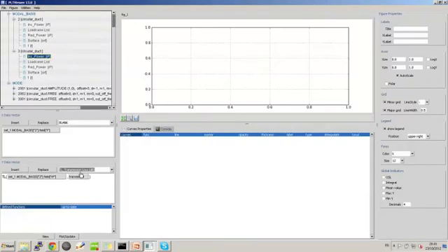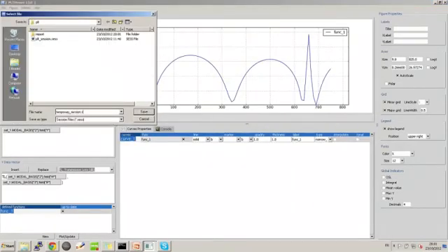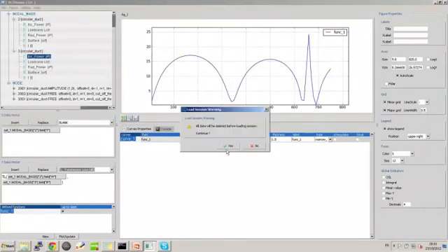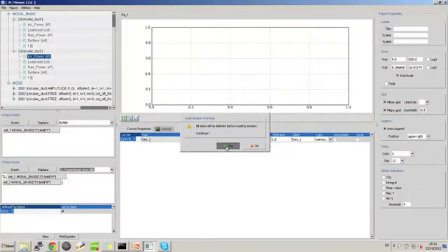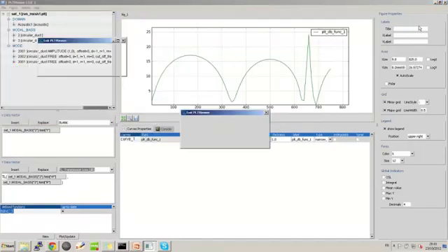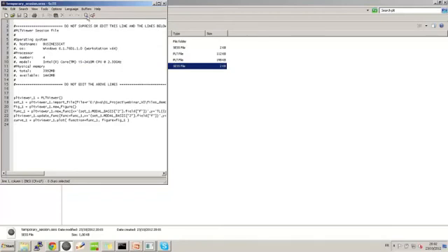So here again, I could save this session by calling it temporary session.sys. And again, I can just replay automatically my session over and over and over. Now, if I want to visualize my two outputs from my two different meshes in one session file, I can make a small addition in here, so that in case those two PLT files are changing all the time, I can just replay the session without changing anything.